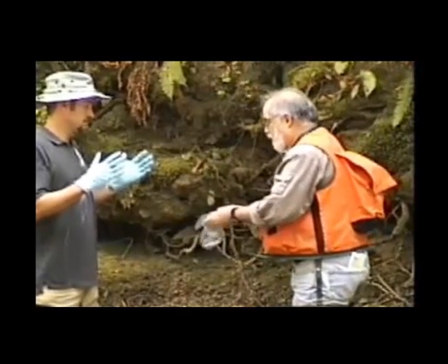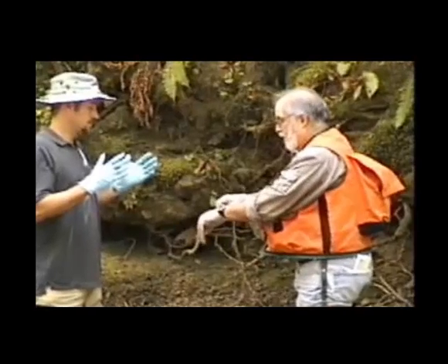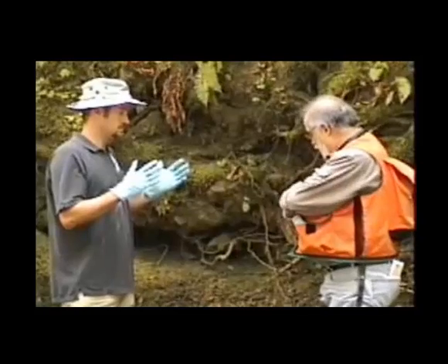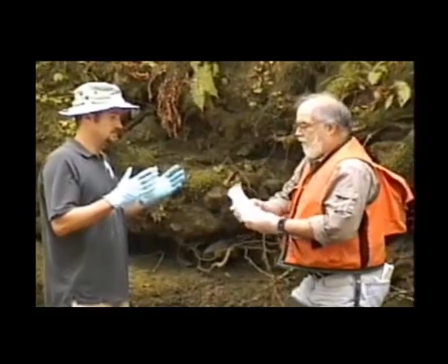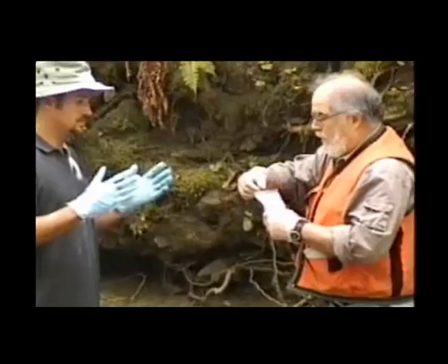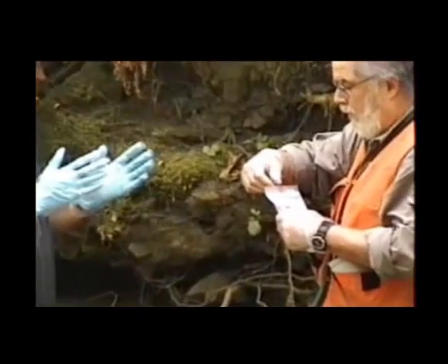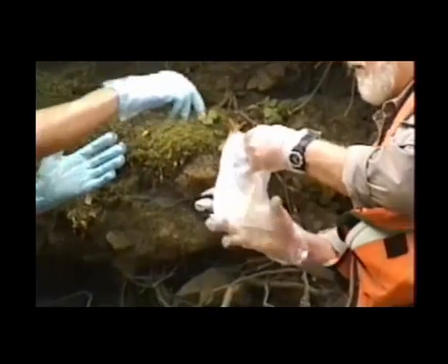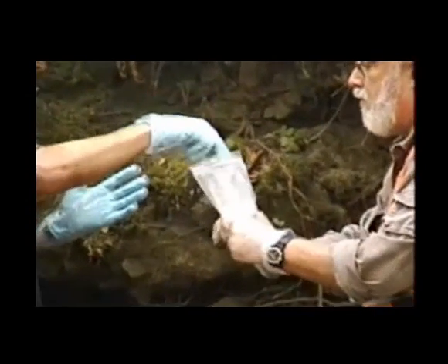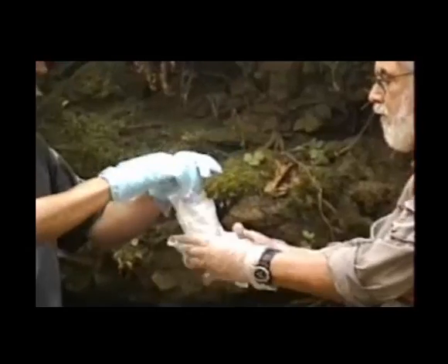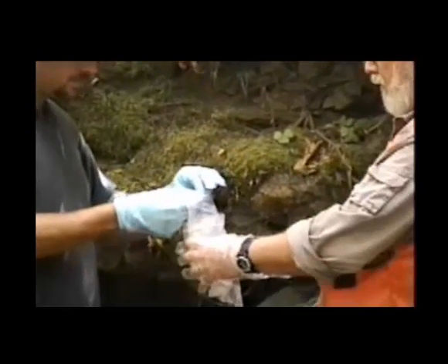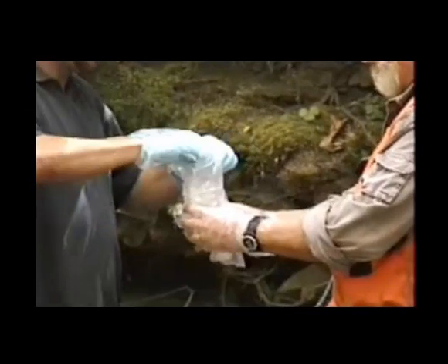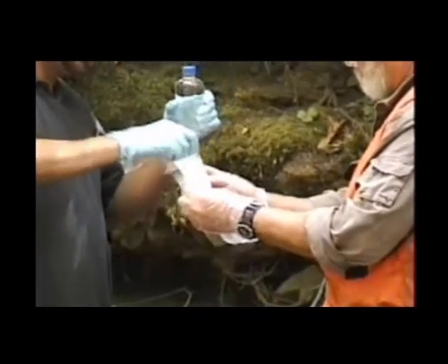When dirty hands is sufficiently gloved up, dirty hands then removes the sample pouch. It's a double bag. The inner sample bag contains the sample container. The outer sample bag can be touched only by dirty hands, and then clean hands can touch only the inner sample bag. Notice that clean hands then removes the sample container, puts the clean inner sample bag back into the outer sample bag,